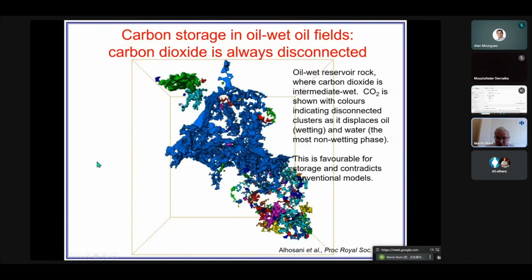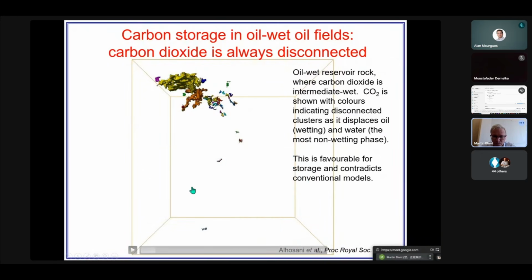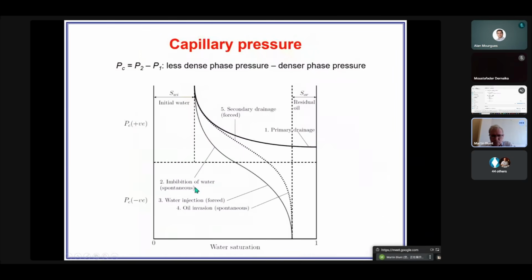So this is the first misconception, probably of all of them in today's session, the most nuanced, because unfortunately, I don't have a clear answer, right? Still very much work in progress. But for those of you who are studying CO2 injection with enhanced oil recovery, I would very strongly recommend that you actually make measurements of the CO2 relative permeability in the presence of mobile water.